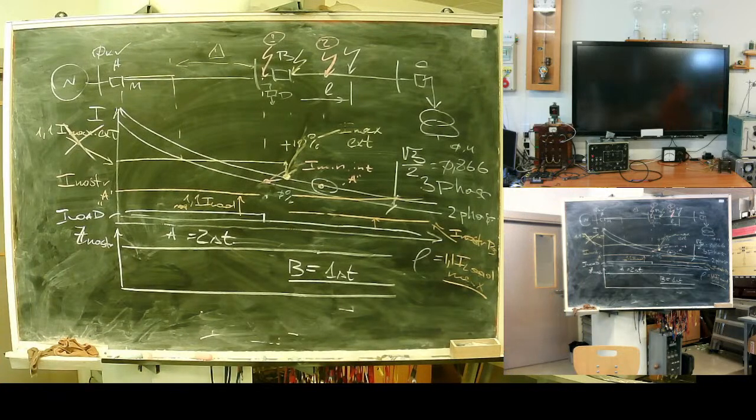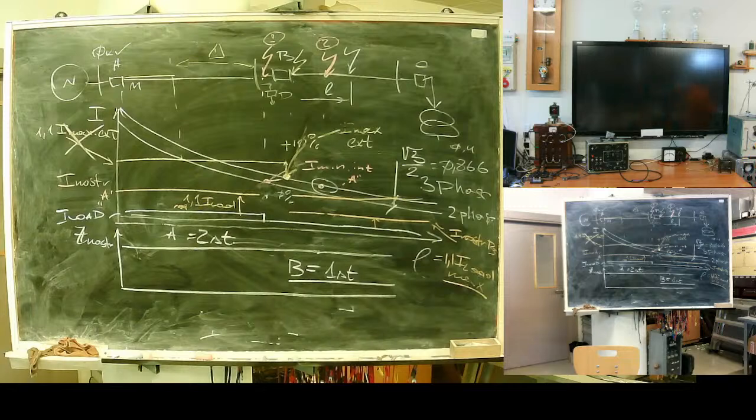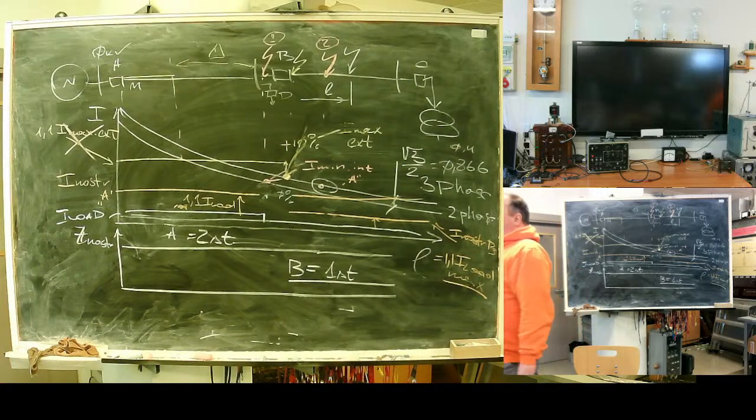What time is necessary for a circuit breaker to interrupt an arc? For a very old circuit breaker, it may be 2-3 seconds. For 1960s designs, it may be half a second. New circuit breakers do everything in less than 200 milliseconds.